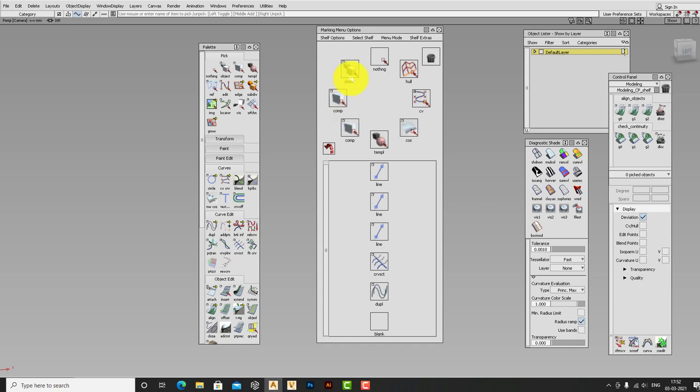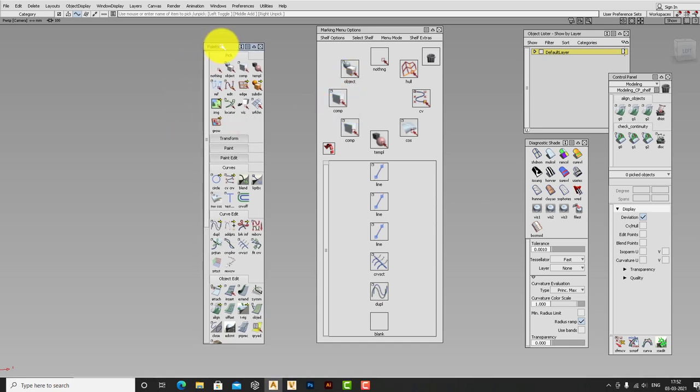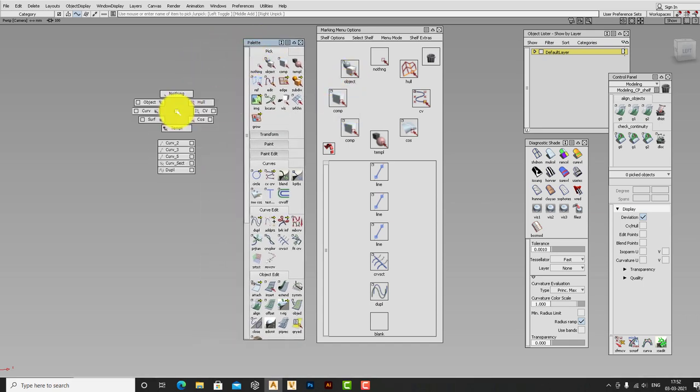Now one more interesting thing here is, if you go for left click, I have given an option like pick surface, curve and object. Surface means if I go for surface picking, it will pick only surface. When I go for curve, it will pick only curves. And when I pick for object, it will pick anything including canvas, like curve, surface, canvas, anything. Okay, other than locators and template, everything it will pick.